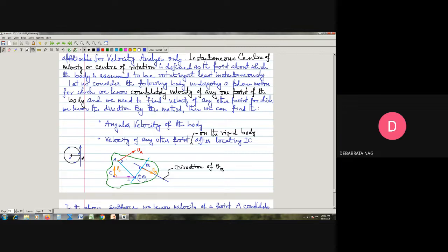the velocity vector. So if this red line is the known velocity vector for the point A, I can draw a line, this indigo line here, perpendicular to the velocity vector. It can be produced in this direction or that direction, of course. Now, since we know the direction of the velocity of B, I can similarly draw another line perpendicular to this direction and allow these two perpendiculars to intersect at this point.